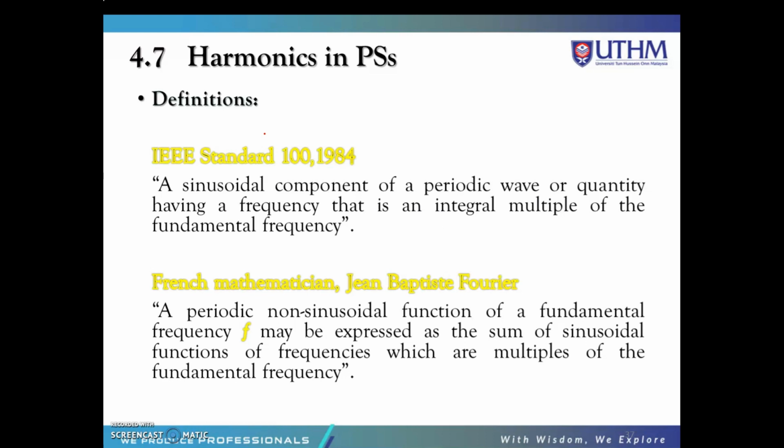Okay, next section is about harmonics in power system. If we refer to the IEEE standard, harmonics is a sinusoidal component of a periodic wave or quantity having a frequency that is an integral multiple of the fundamental frequency.